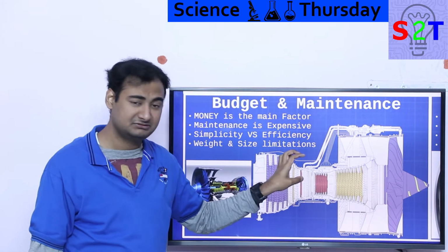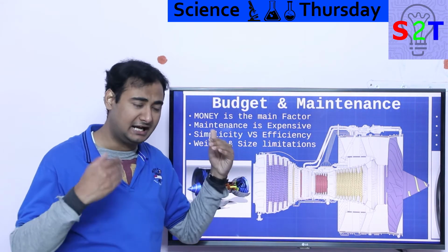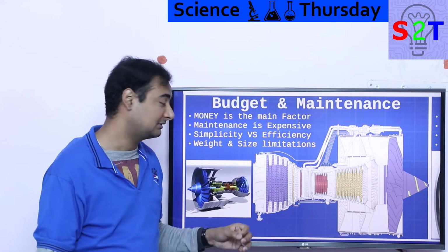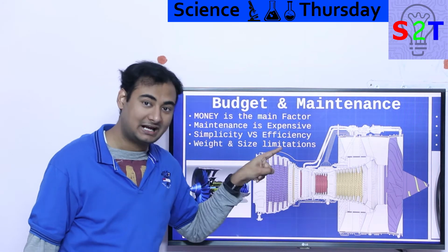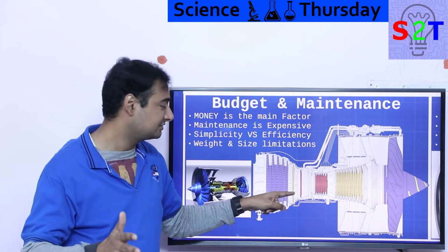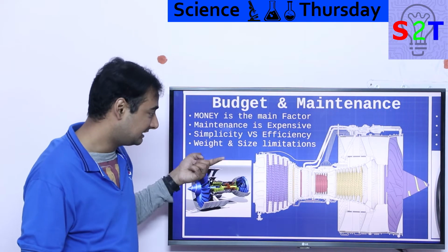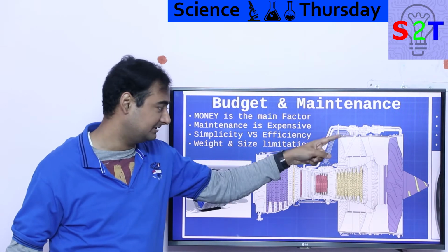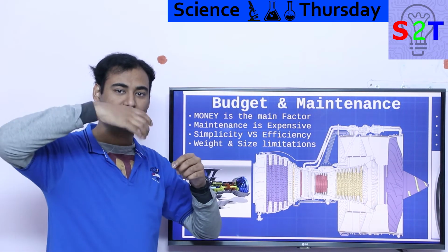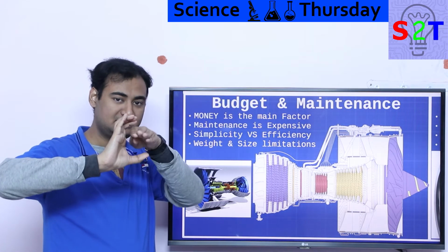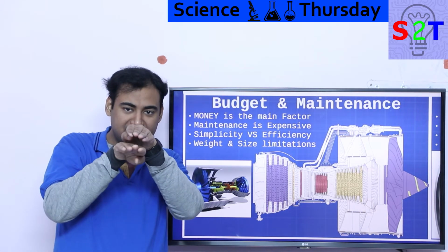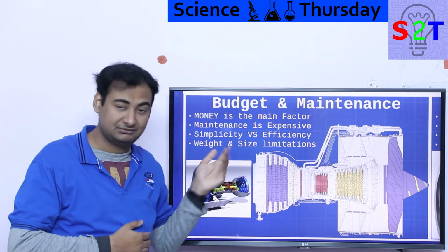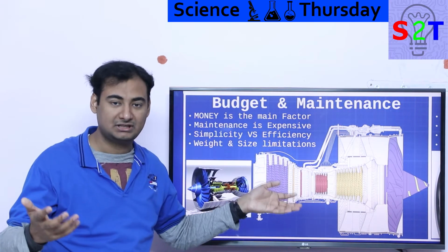Now, there is a second, higher compression stage. The higher the compression, the better fuel burning efficiency you get. So if people want YOLO amounts of compression, there is one. Again, to drive this at a higher RPM, say 12,000 RPM, there is another turbine. So you can understand there is one shaft, and that shaft has three independently rotating things. Basically, you have one shaft rotating at, let's say, 3000, another shaft rotating at 6000, another shaft inside that rotating at 8000 or 12,000, whatever the case may be. So you can understand, even though it's quote unquote simple, it's so complicated.